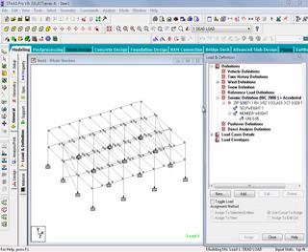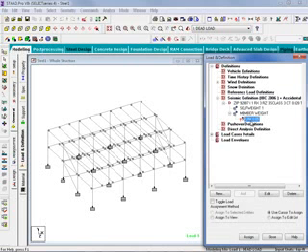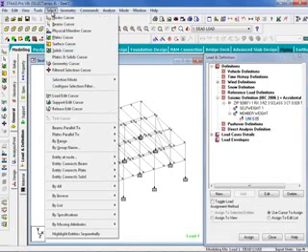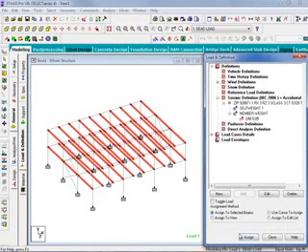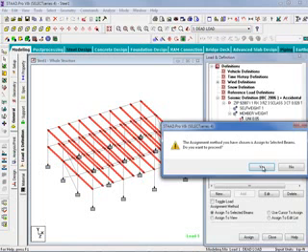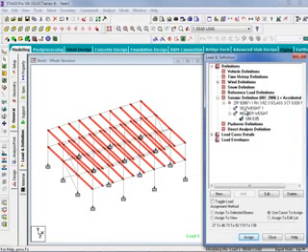In the Load and Definition dialog, we're going to notice that our self-weight item has automatically been assigned to the model, but our member weights for our uniform load still need to be applied to the model. To do this, we will select this load item, then select the members to assign it to. For this model, we will go up to our Select menu bar item, select Beams Parallel to, and then select our global Z-axis. Once your members are selected, we will change our assignment method to assign to selected beams and then click Assign and confirm with Yes.